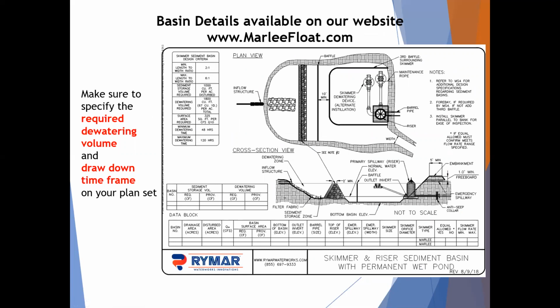So we have the required dewatering volume now and the sediment storage volume on this detail. Here you can see the skimmer set above the bottom of the basin, so this would be your sediment storage volume. We have a place here to put that in, as well as dewatering volume. Everything else is pretty similar, and we just added to this column the required sediment storage as well as the required dewatering volume.